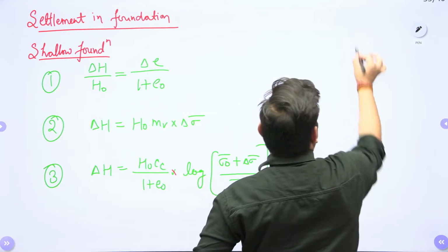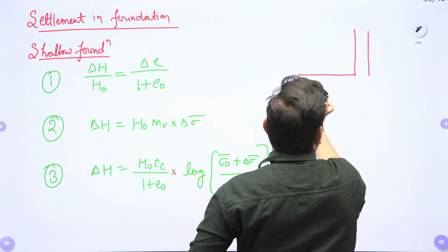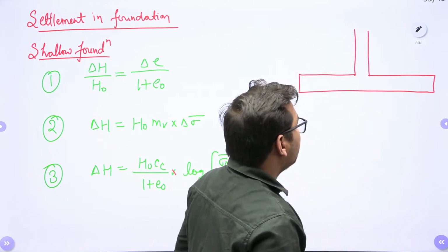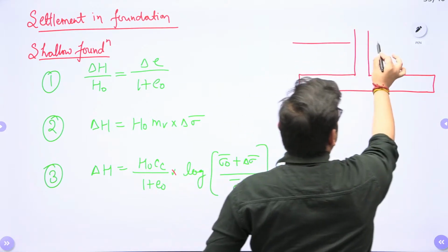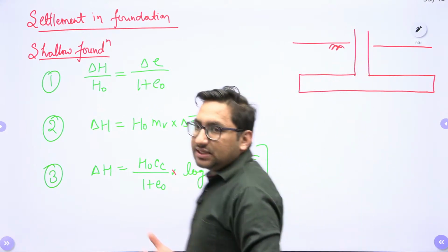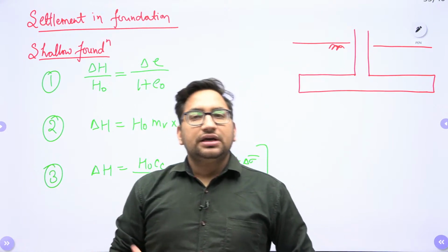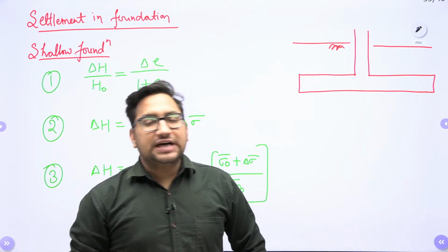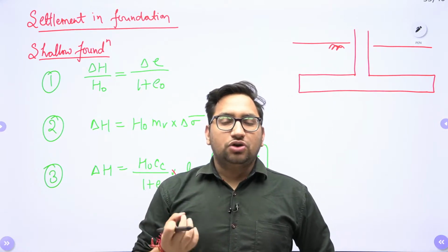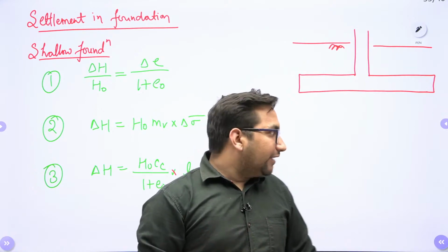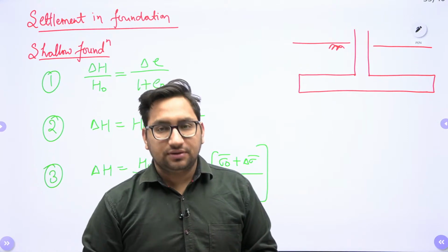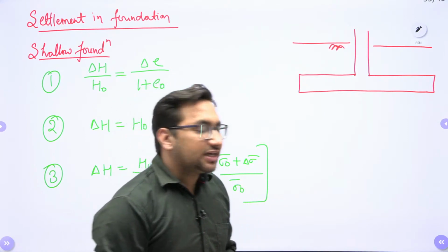Let's suppose this is your particular foundation, right? Always remember, we are more concerned about the settlement of your clay layer, as we know that in sand the settlement will be completed within the construction period only. It means after the construction of our structure, the settlement of sand is not going to bother us. The effect will be mainly due to the settlement of your clay layer, right? So we take into account the settlement of that clay layer only.